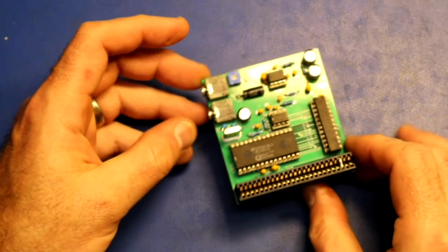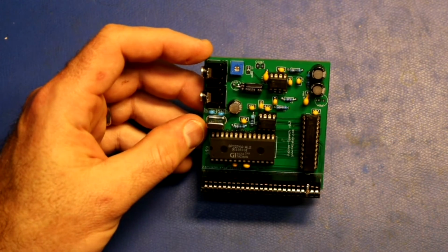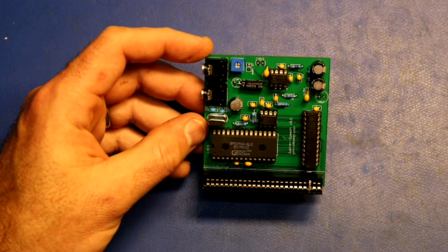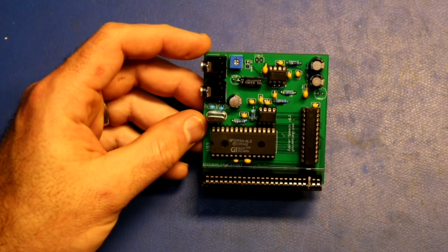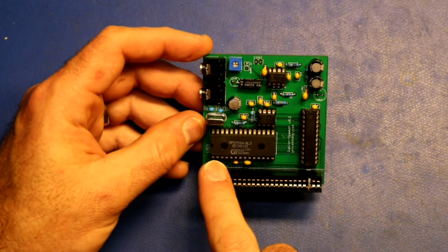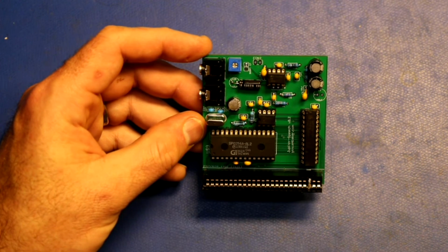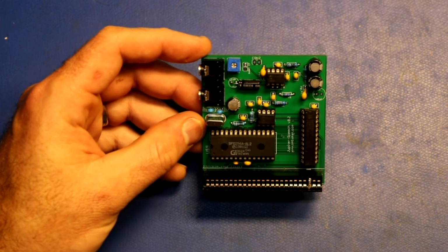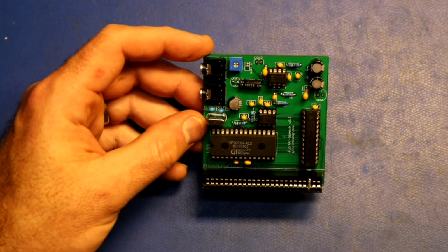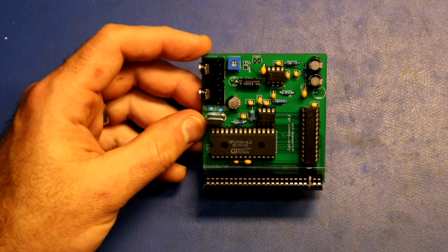And then finally, this last one is a speech synthesizer. That's always my first project with every one of my retro computers, a speech synthesizer. And I did it here as well. So we've got the SP0256A-AL2, that's a phonetic speech synthesizer. Very popular chip, was sold by Radio Shack for a long time. You can still get them on eBay. Be a little bit careful of counterfeiters.